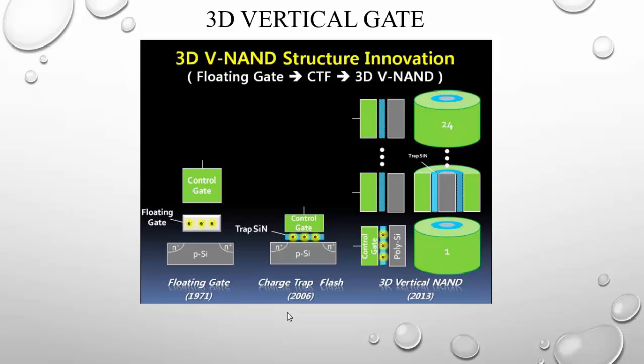So there are other benefits to using a charge trap though. Charge traps require a lower programming voltage than floating gates. This in turn reduces the stress on the tunnel oxide. Since stress causes wear in flash memory, the lower programming voltage gives a charge trap flash greater endurance than conventional floating gate.